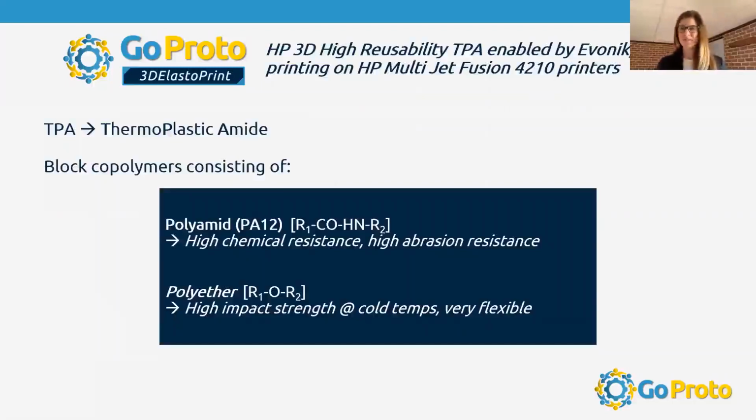And so this is very close to the Shore D40, because that's typically what we talk about on the injection molding side. And we do have Shore D40 granules that can be used for molding. If you want to prototype in this material and you want the same chemistry, same kind of performance to transition to the injection molding. And I think GoProto can help with the injection molding, and we can get them granules that would be very similar to this material that you would prototype with.